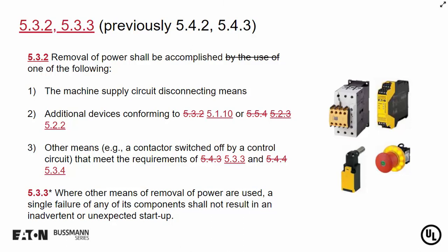For example, if you were using a PLC, you would have to make sure that PLC would be a type that would be a safety device, to be able to provide reliability in terms of making the means of removal of power safe and insured if you do have the need to work on a piece of equipment.